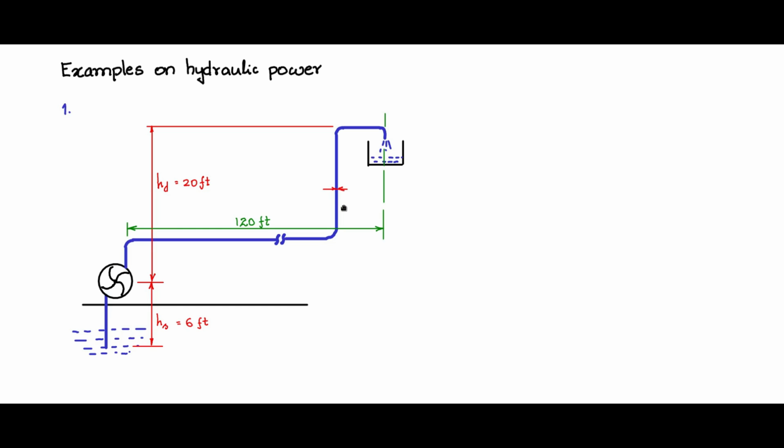Most of the homes in recent times use pipe diameter of 1 inch, again depending upon the number of people in the household, and mostly PVC pipes are used. So recall that for PVC pipes, the inner surface is very smooth. The surface bumps are negligible, and therefore the roughness ratio is 0. So that is an advantage.